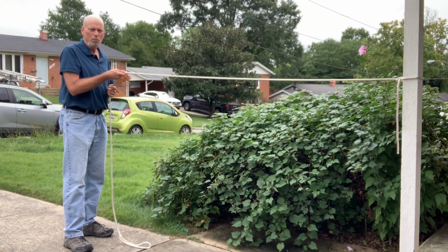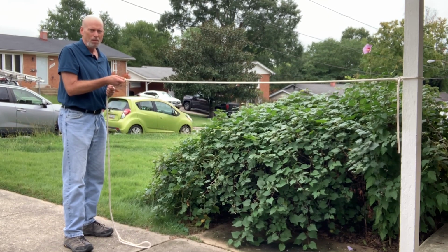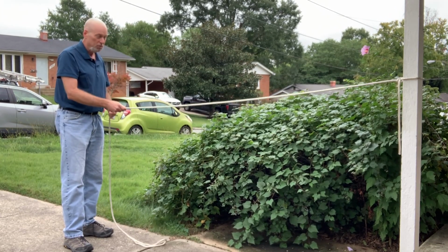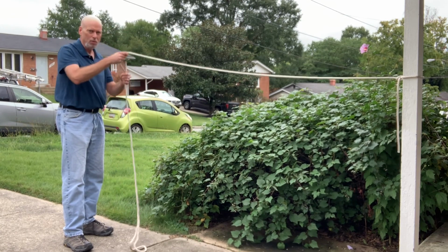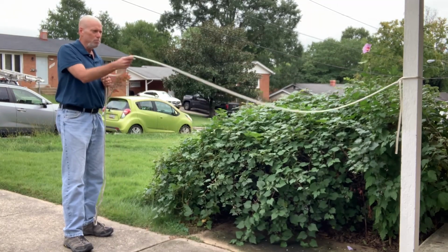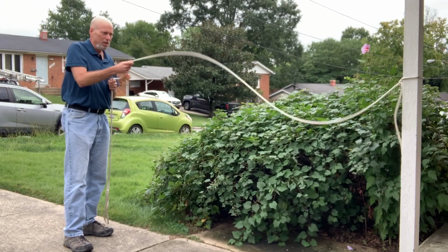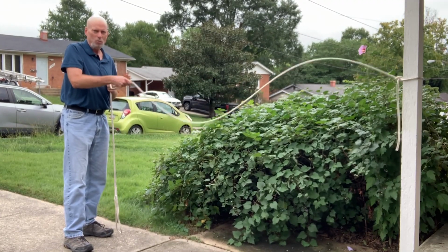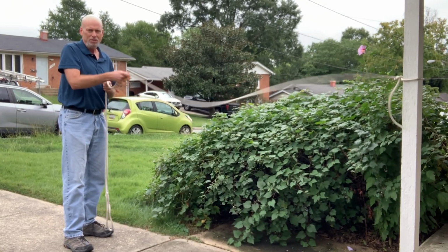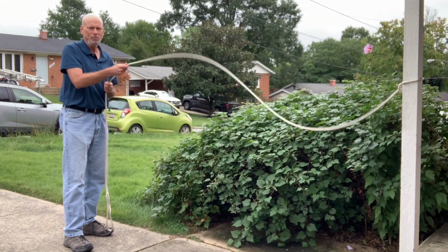We can illustrate the general principle with a simple mechanical analogy with a rope tied down at one end. If I move my end of the rope up and down very slowly, then the entire rope moves up and down essentially as one unit, or as we call it, a lumped element. If I start to move my end of the rope more quickly than the energy can propagate down the line, then we see that the energy is propagating down the rope as a wave. And I've even set up a standing wave on the rope. And the same general principle holds true for electrical signals on a transmission line.